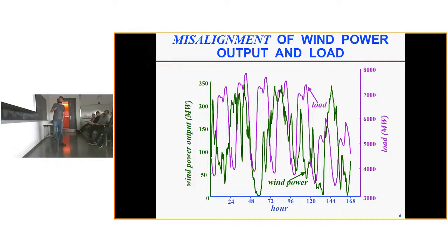And so there's a big problem with this because wind power is not aligned with the load. In fact, many times it is going down when the load is going up. We have more wind power at night than during the day. And this imposes higher ramps for the controllable resources to meet. So for example, in this moment, we can see that the load is ramping up when there's absolutely no wind at all. And here the load's going down and the wind's going up.